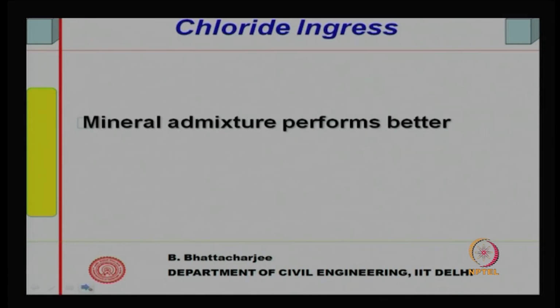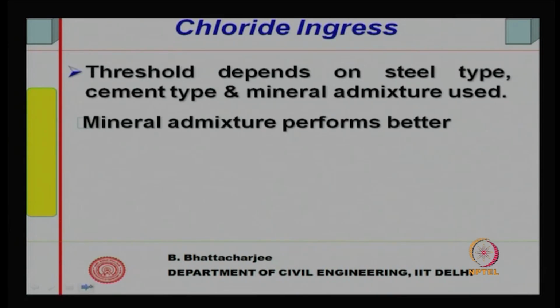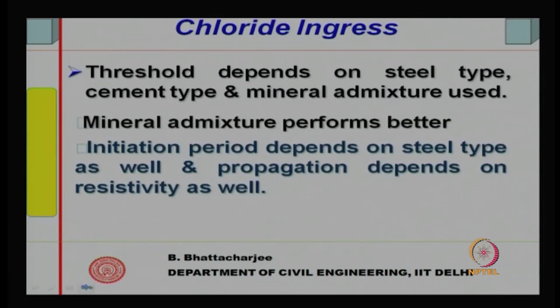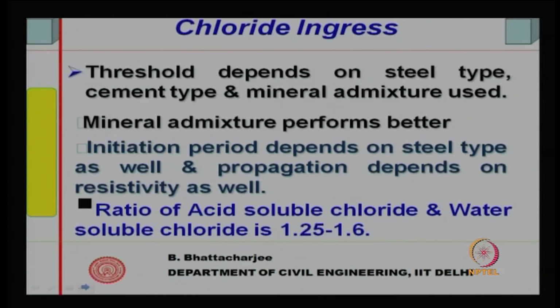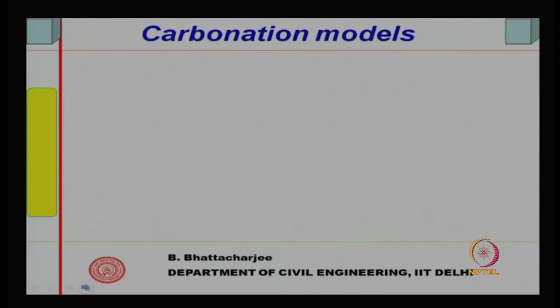So, mineral admixtures therefore would perform better, because they tend to increase the resistivity, right. So, this mechanism etcetera we will look into sometime later on when we look at durability. So, this is important because resistivity is an important issue and it reduces the corrosion rate. So, this we can look into later on.